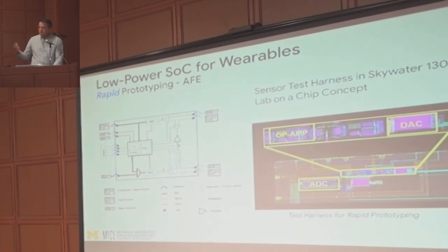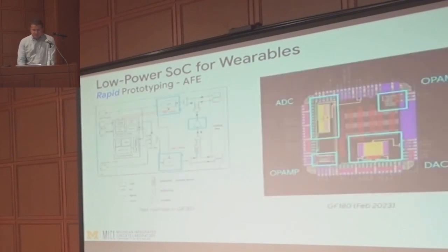Why I'm mentioning this is because Fitbit reached out to us and they wanted to create low power circuits using our OpenFASoC software. As we started this collaboration, we created our front end, which is basically a lab-on-a-chip concept. We taped out in SkyWater 130, using ADCs, DACs, and so on. Again, 3 months later, we did another tape out in GF180. With 10 students, we were able to crank out all these chips. And again, we didn't use a generative approach here, but we used a lot of the layout and methodologies we're using for SkyWater 130, and we were able to tape out this chip here, GF180.